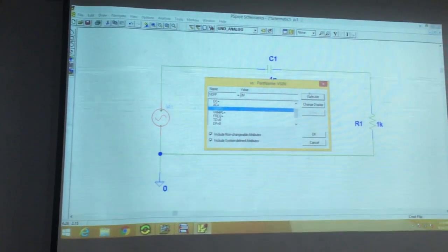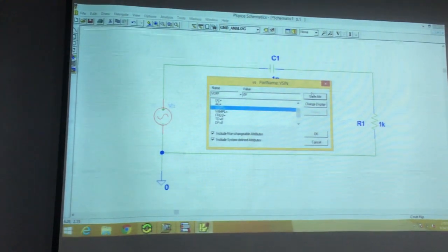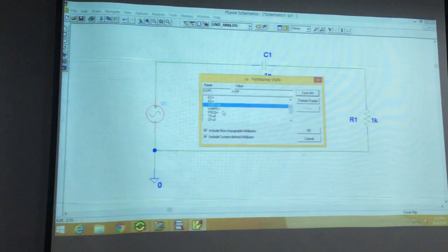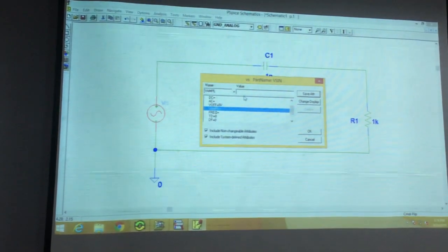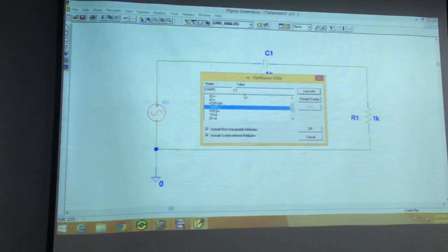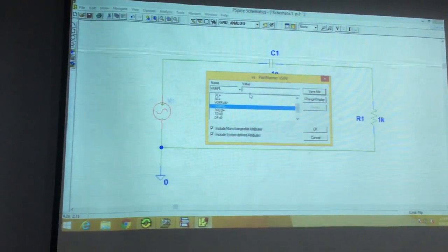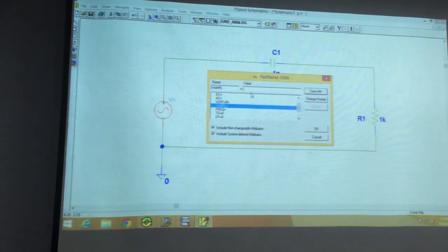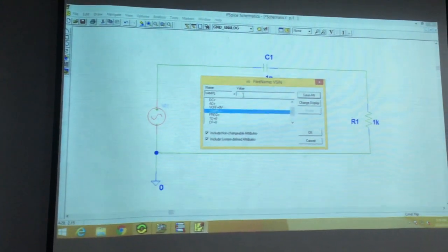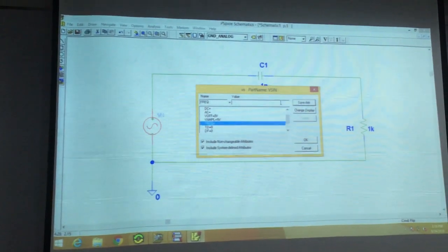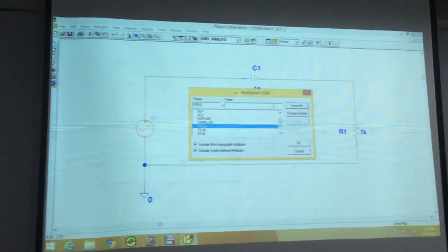And then either save attribute, click on that button or press enter. Anything is just fine. Done. Now, next guy in line, VAMPL. This is what we need. This is known as the amplitude. Okay? The amplitude goes like 5 volts. So we need to set it to 5 volts. 5V. Enter. Done. Then the last one is the FREQ property.